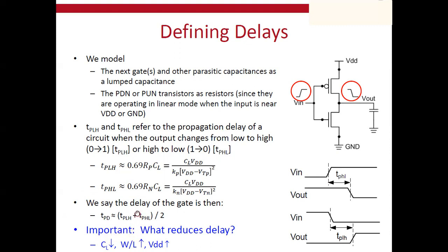So you can never eliminate or remove the effect of the propagation delay. However, you can play with adjustments, through the W/L factor or even the VDD factor.